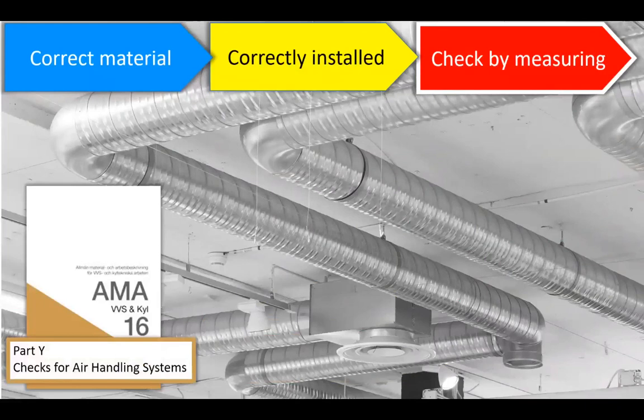No, you shall divide your installation in manageable portions. Around 25 square meters, I recommend. 20 square meters is my minimum. Oh, I'm afraid this will take a long time. Is it necessary to test the entire system? Can I just test samples?